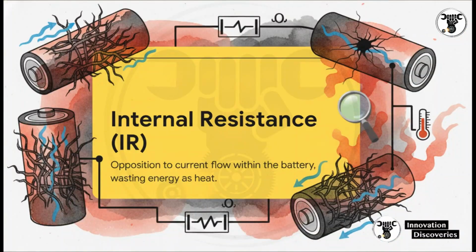You see, countless batteries are tossed, and perfectly good systems are misdiagnosed every single day, just because people only look at voltage. But voltage is only half the story. The real villain here is internal resistance, or IR. Every battery has it. It is literally the physical opposition to current flowing inside the battery itself. Think of it as a hidden resistor connected directly in series with your battery's ideal power source. We measure this in milliohms.